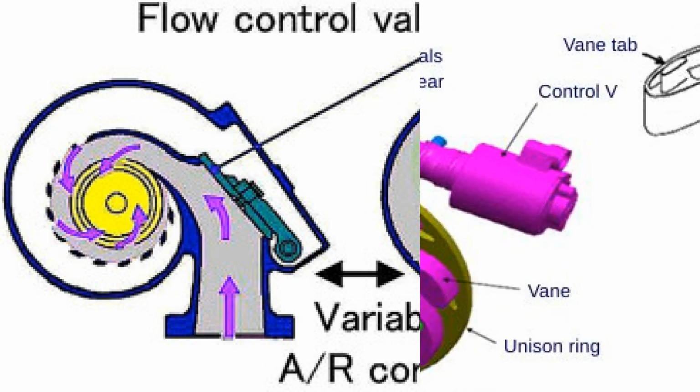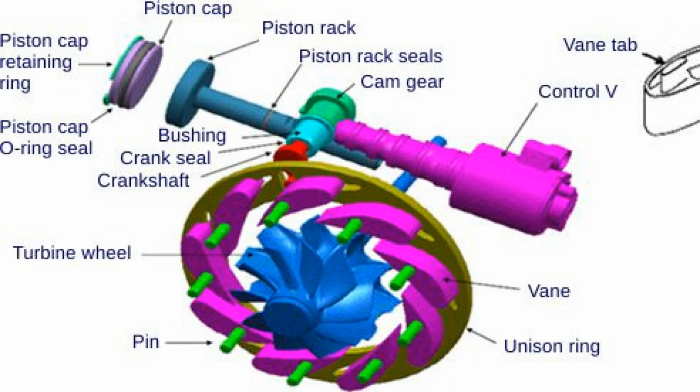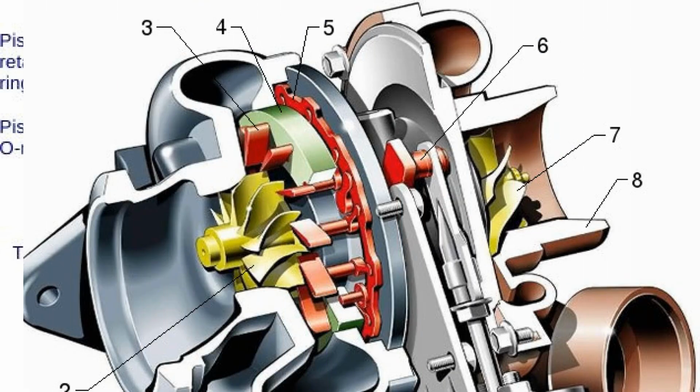Advantages: active modification of the channel cross-section of the hot part of the turbine allows expansion of the effective operating zone. Cars with variable geometry turbocharging can produce more power from low speeds. Reduced exhaust gas pressure at high speeds. Due to the absence of the wastegate valve in the hot part, the number of multidirectional gas flows is reduced, which improves the flow of gases through the turbine. Improved engine elasticity. Reduced fuel consumption and emissions.